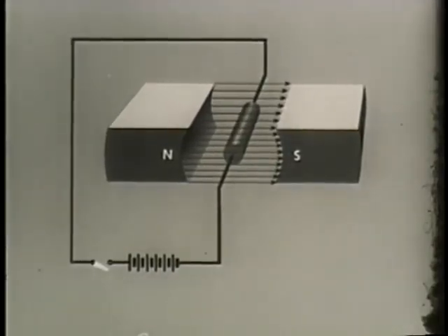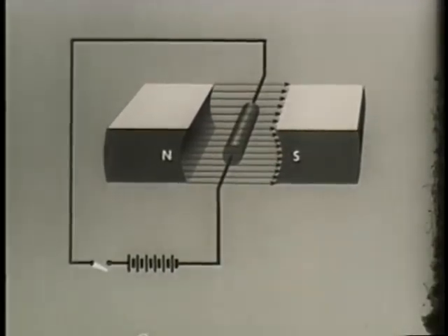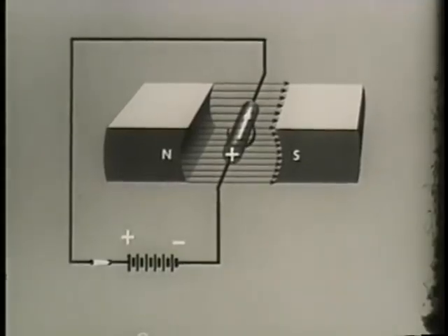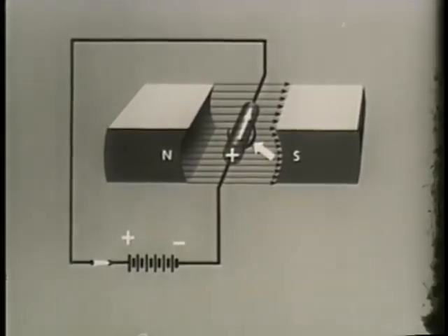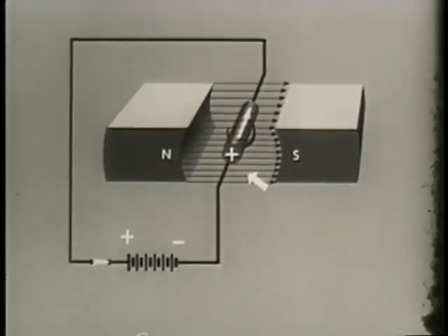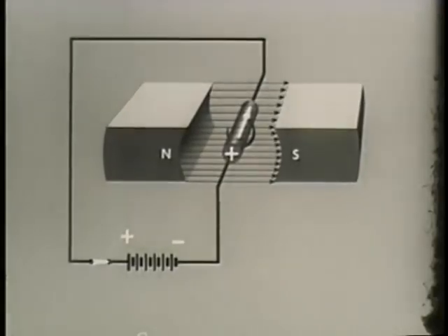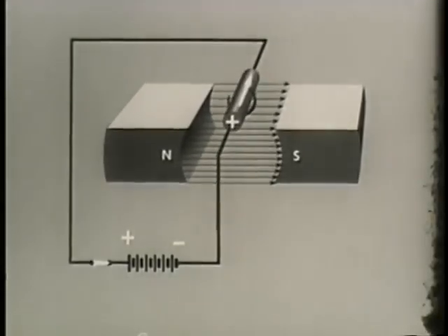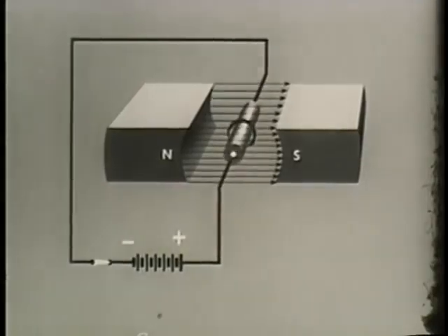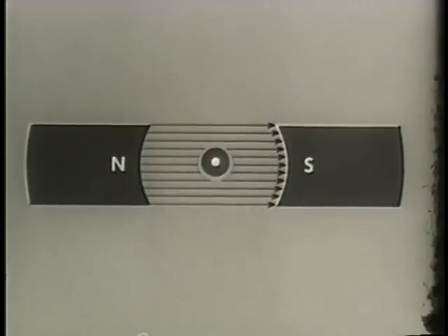To see what really happens, let's go to a drawing again. Here, a conductor is suspended in a magnetic field. Current flow from a power source creates its own magnetic field in and around the conductor. This field around the conductor reacts with the main magnetic field to cause motion of the conductor, either out of the field or into it. The arrow point indicates the direction of the current flow in the conductor. In this case, the flow is toward us.